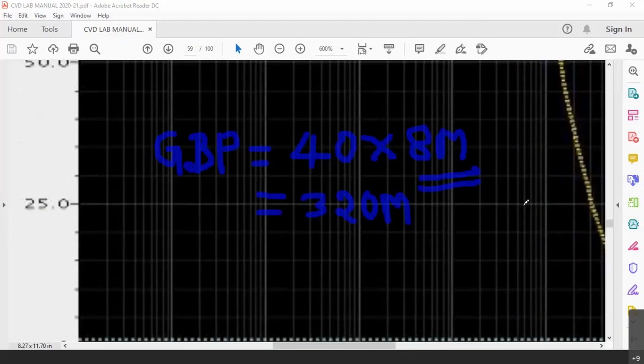But we know that in the case of MOSFETs, there is a lot of parasitic capacitance. And how do we increase the bandwidth? In the case of MOSFET, that is the challenge. That is where we use BJT also. We have a technology called bipolar as well as CMOS. Now bipolar can give us a larger gain, and it can give us a larger bandwidth when compared to MOSFETs, because in the case of a BJT, the parasitic capacitances are lesser in their value when compared to MOSFET.